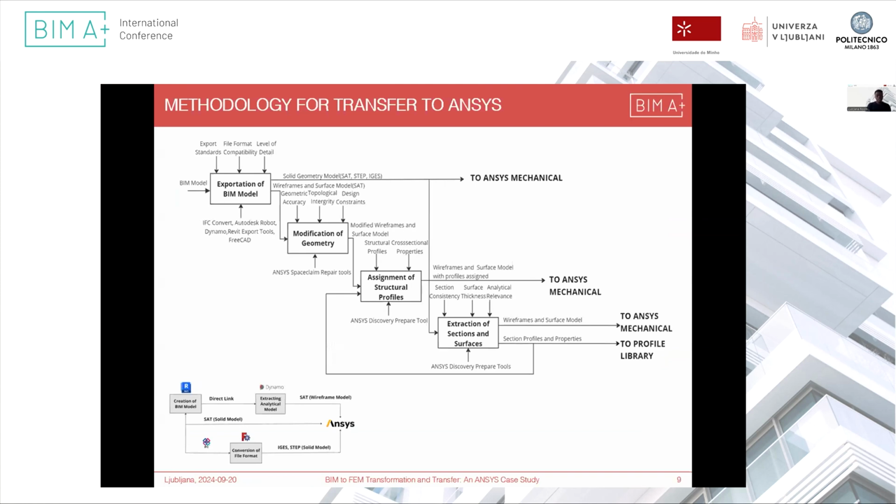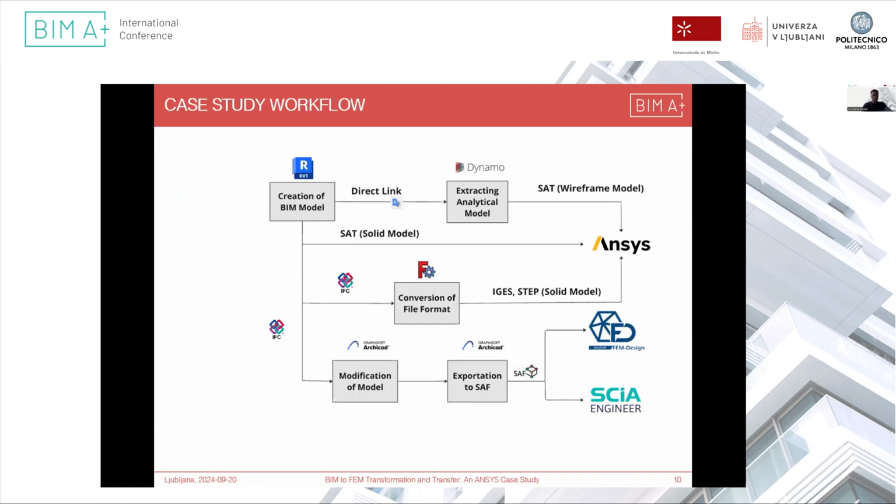And as I mentioned, the extracted sections and surfaces can be stored in the profile library, which can later be assigned to any new lines and wireframe models imported into ANSYS. So that is how the BIM model was transferred from the BIM environment to ANSYS.